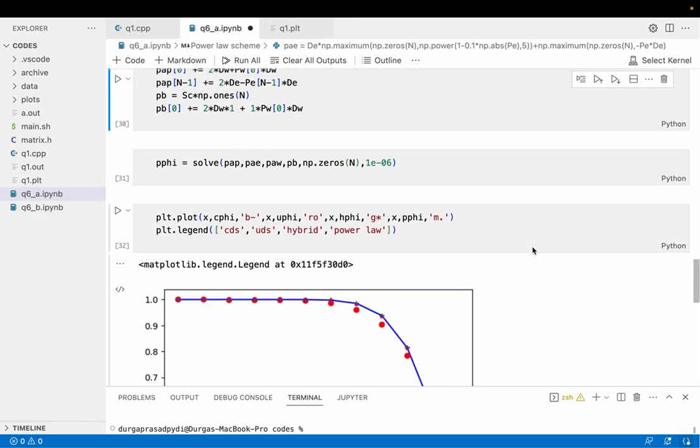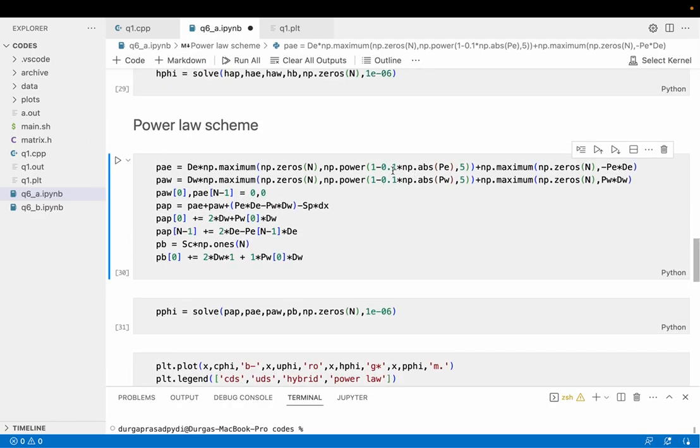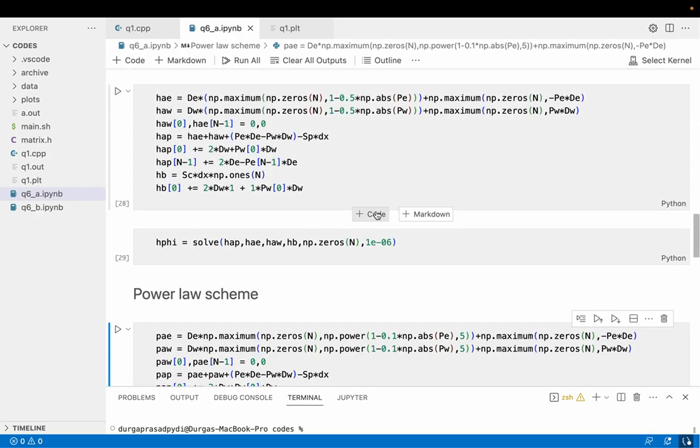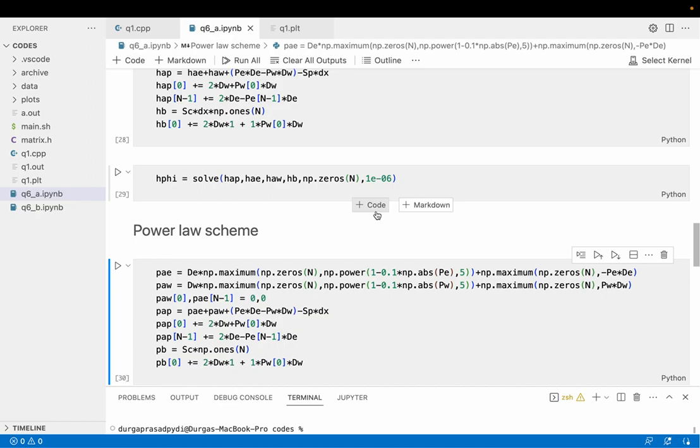I have not included that here, but the idea there is instead of using power laws or anything, you can use directly an exponential function, and then maybe you can go through the reference book provided in the section. Patankar explains the exponential scheme as well. Usually power law or hybrid is where you will get most physical results, so you don't have to go to exponential. That is computationally more expensive than this. So I stopped with this.